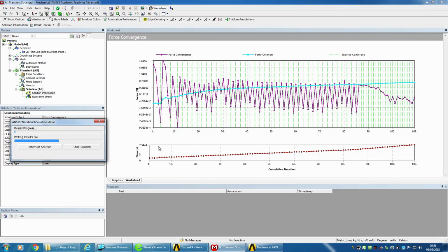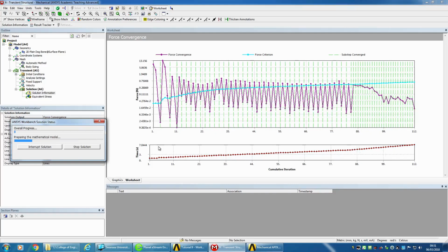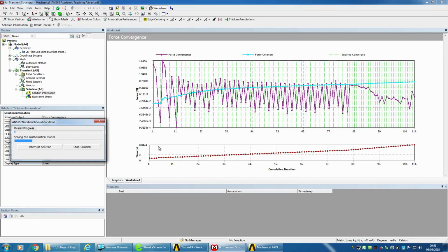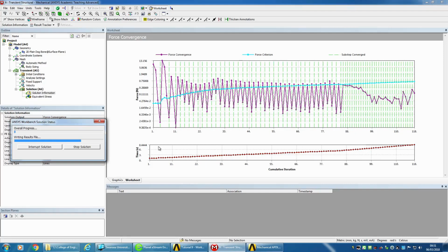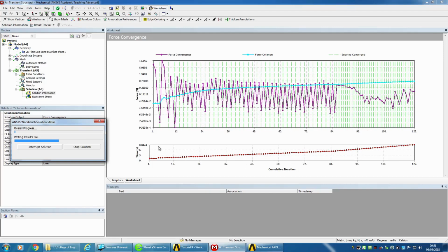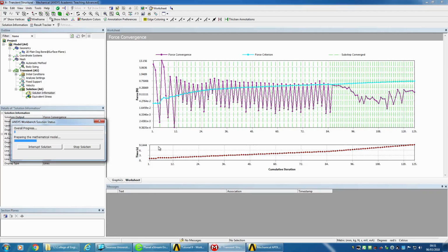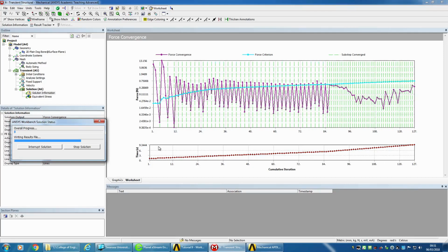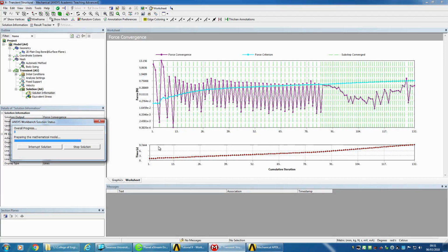When you enable some of the nonlinear plasticity-based solutions which are available, which we're going to go through in a bit more detail in the properties in a minute, post the elastic yield point, it becomes a very complex nonlinear problem. ANSYS handles it in the best way it can, and it does quite a good job. Through the plasticity and the hardening rules, you get the non-returnable deformation post the elastic yield, and it does quite well.